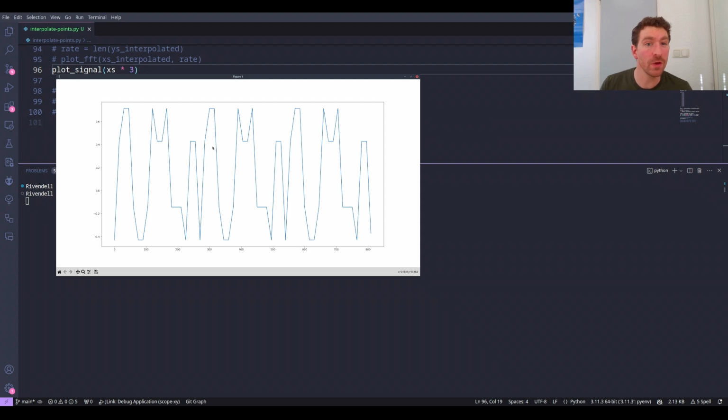Now, something to note here is that this actually still has a lot of high frequency components. We're still moving from this point to this point really quickly. We're still dropping all the way down here. So it's not quite enough to think of filtering out just to pure sine waves. You need to filter out all of your switching and the PWM switching noise, but still keep in enough frequency so that you have this.